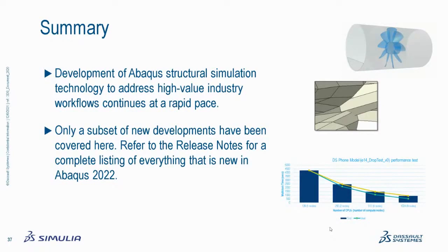How is the scalability of HPC for Abaqus Standard? So I presented some of the data there, in particular for the new Iterative Solver, where you could see problems of 50 million to 100 million degrees of freedom going up to 1,000 compute cores. I didn't present any data on the Direct Sparse solver, but again, we're seeing very good scalability, 500 and even up to 1,000 cores.